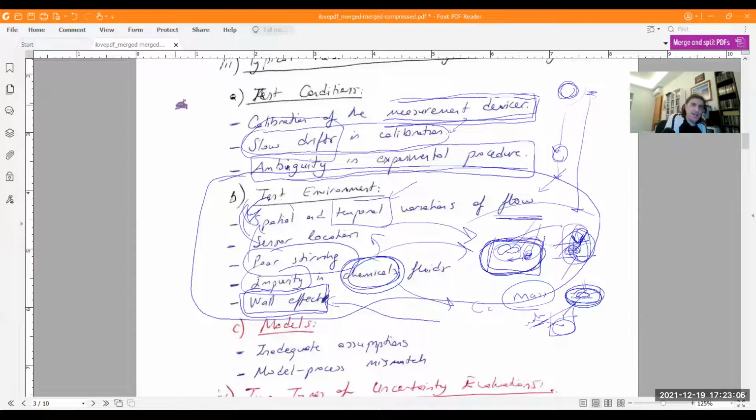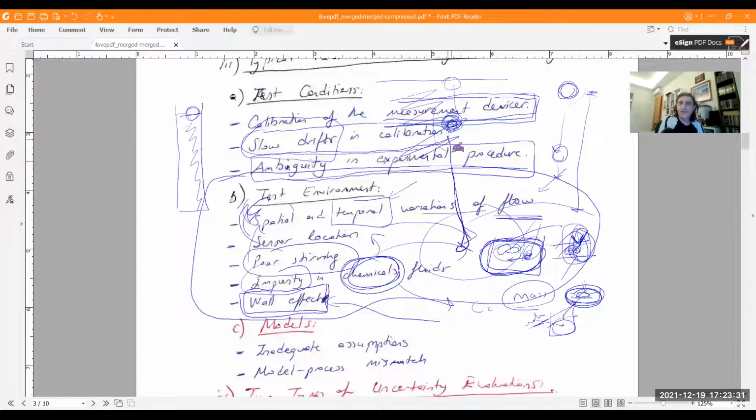On the other hand, when you conduct a similar experiment in a fluid, let's say with metal balls, the idea is still the same. This experiment will not give an identical result compared to conducting it in an ocean, because in the ocean there's not going to be a wall effect. It's going to be very deep, so the terminal velocity is going to be reached somewhere here. There's a very long distance.